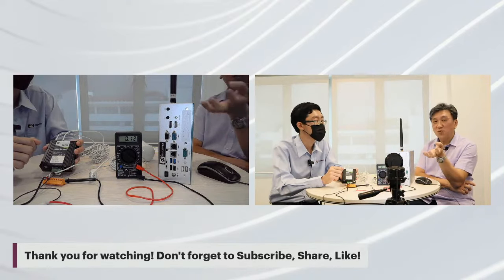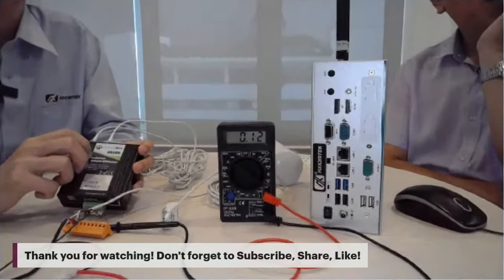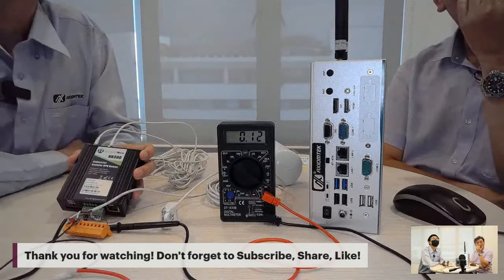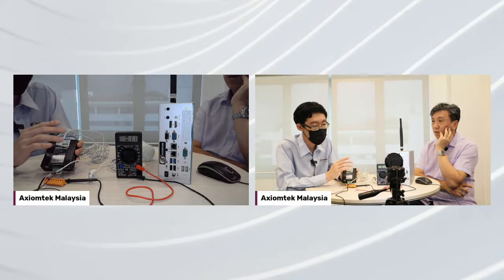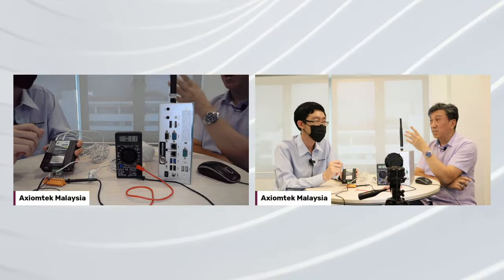After doing the measurement, you can see it is right now consuming about 110 to 130 milliamps. And when it is connected, roughly how much current is consumed? When everything is connected to the 4G network, the current is around 200 to 300 milliamps. 200 milliamps when connected, but when you transmit data, it can go up to 300 or more milliamps.